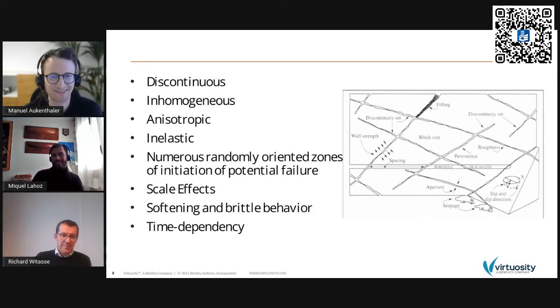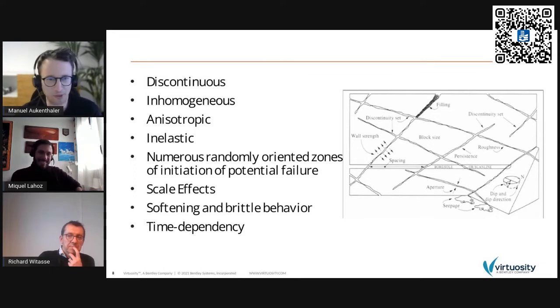That's true. The moment where you have water circulating in the discontinuities, things start changing. It creates pressure that contributes to open them. So it changes the friction properties of these discontinuities. And also, since most rock is either non-porous or has non-communicated pores, water can only flow through this discontinuity network. So then you can have very large volumes of water in a very short time. Yeah. I mean, water, when we talk about soil, when we talk about rock, it's always the biggest enemy and a friend, maybe at the same time.